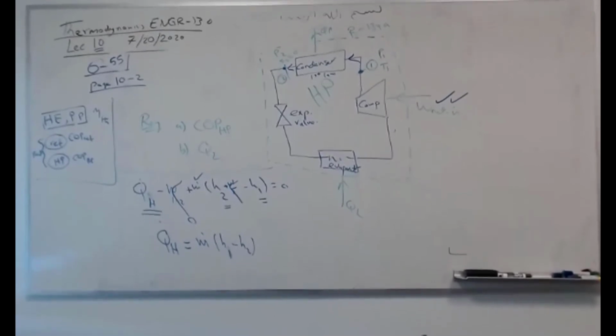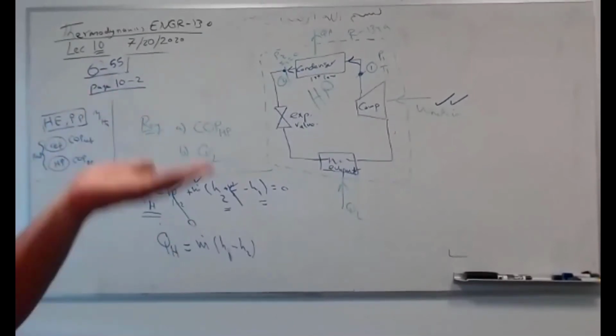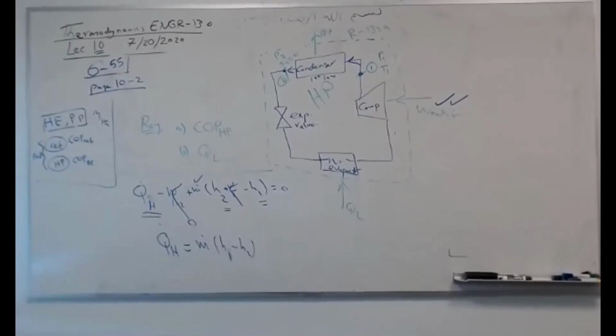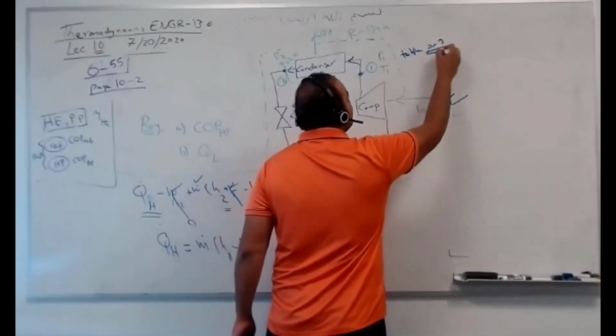Go to the steam table, open the first page, you will see the tables. Is it A13? Exactly, 11, 12, 13, 14, 15. This state one is superheated. It means the table, the last one, 14? Okay, guys, A14. Oh, actually 13. 13 is the superheated one. 11, 12, 13. So 13, exactly the superheated. This is table A13. You can obtain h1.